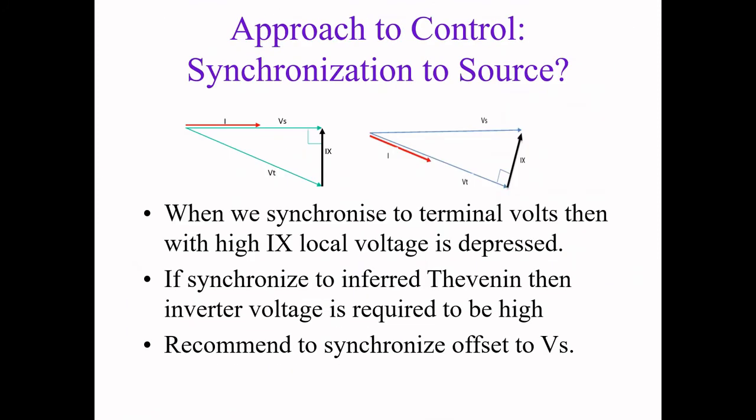In these diagrams here, controlling the angle of current essentially controls the magnitude of terminal volts. And so we might have a broadcast angle of VS, but then modify it for the sake of local terminal volts. But you would be able to much more easily put limits on it to manage that as a slower outer loop, with the fast loop being the current following the current reference.